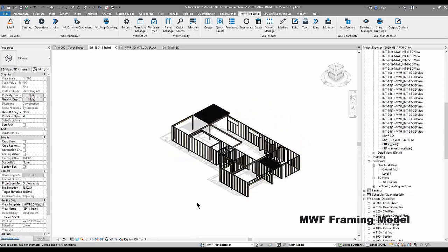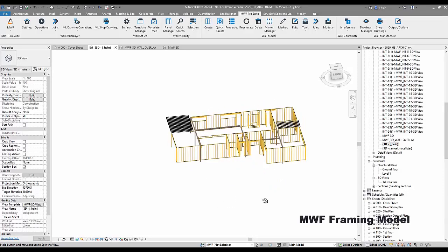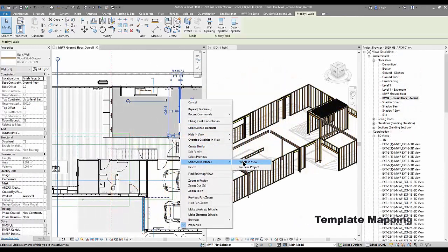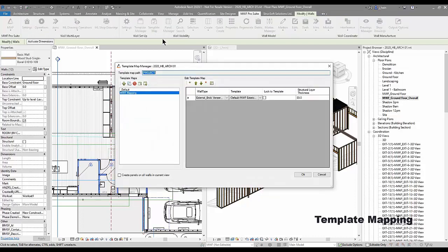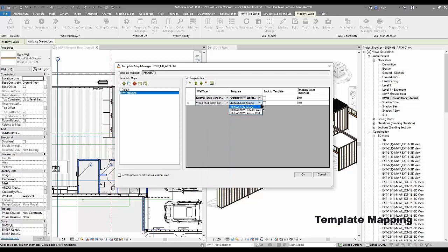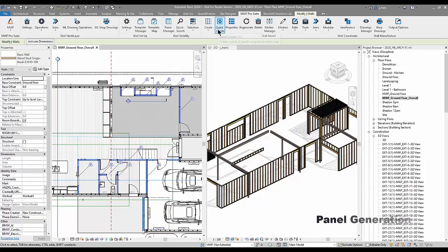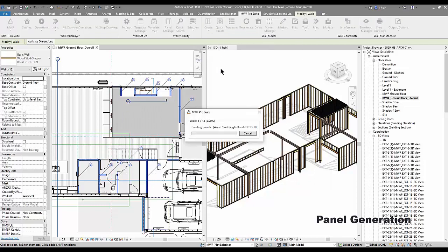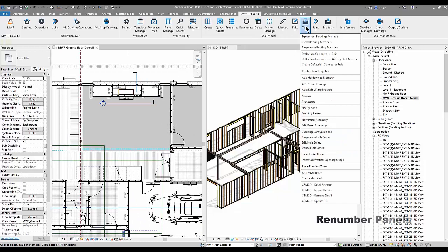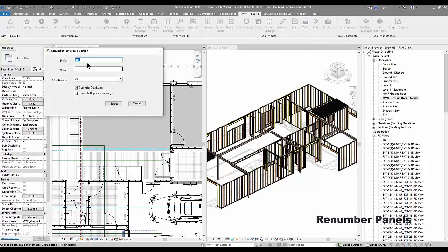So here's my house model, and what Jamie, the expert there, has done is he's created a setup for the timber partitions inside the model. He's worked out where all the openings are going to be and what type of timber lintel you're going to need. This is all set up and all automated. So what he can do once it's set up is he can grab a wall and then hit quick update, and it goes and frames everything up based on the settings that we created for this file.